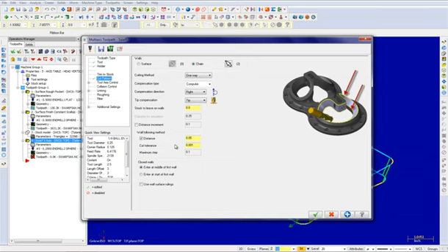The cut tolerance value determines the accuracy of the toolpath and is also used to eliminate duplicate positions as a tolerance when compensating to surfaces. Change this to 0.001 inches. When the distance checkbox is deselected, Mastercam uses the cut tolerance you specify as a tolerance to fit tool positions to the surface based on the curvature of the surface. Otherwise, Mastercam uses the distance value as an absolute distance for the space between each tool position.